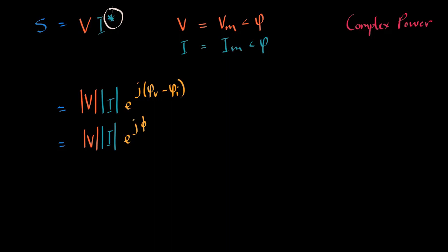If you multiply complex numbers, the arguments, that is, the angles of the phasors, are added together. For our purposes, however, we are interested in the difference between the voltage and current angles. Therefore, we require a difference, so we negate the second argument by multiplying our voltage phasor by the conjugate of the current phasor.